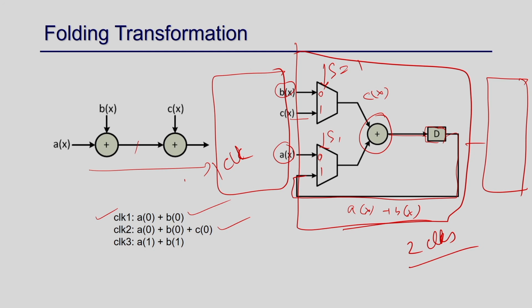If I implement it this way, this module gives the input in every clock, and in the next clock the corresponding output goes to the other module. This is how the synchronization or handshaking happens. They know that every clock they get the next input, and every clock this module will give the correct output.